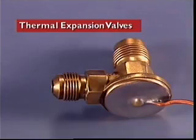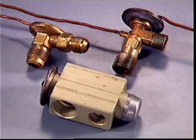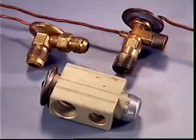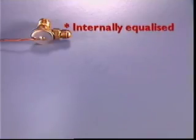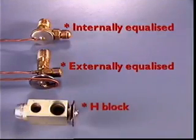The thermal expansion valve, the TX valve, is constructed of cadmium-plated steel or of aluminium. Three types are commonly used. These are internally equalized, externally equalized, and H-block.